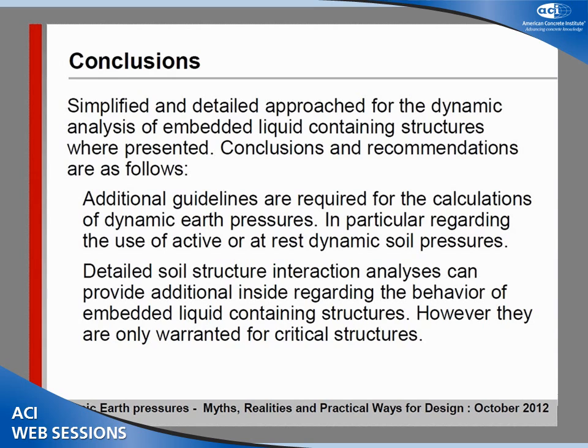So was it based on load combinations like 1.6D and 1.7? I'm asking about the load combinations that are based on the dead load and seismic load. Yeah, the load combinations were based on ACI 349 because I was dealing with a nuclear structure, but if we are dealing with a typical liquid container structure, I guess you would have to use the load combinations in ACI 350.